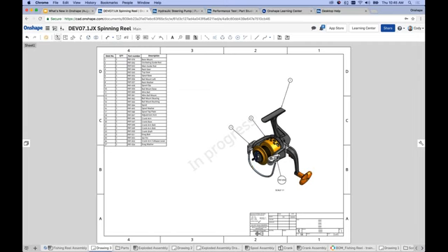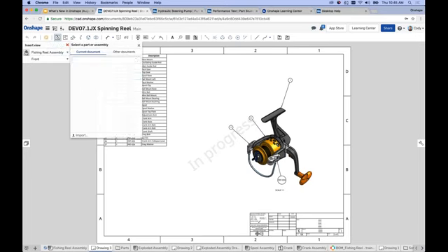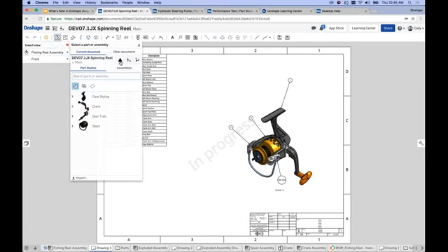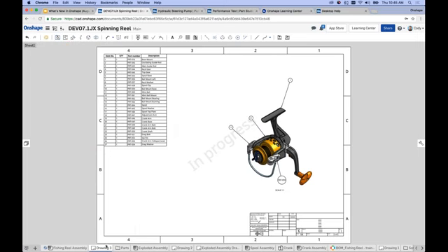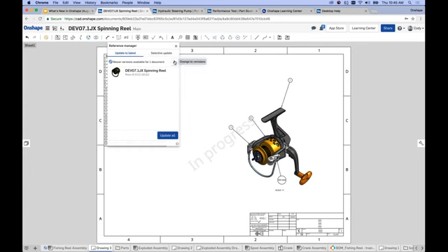Right. Well, now in the insert dialog, when you go to insert your part or your assembly, you'll see a revision view released items filter, right? And you can choose to insert only released items, or more importantly, you can change to version and then filter by revisions, right? And this in particular is what's new with this update. And the reason I mention that is, again, we get asked the question often. I've released part A, now we're ready to make a drawing of it.